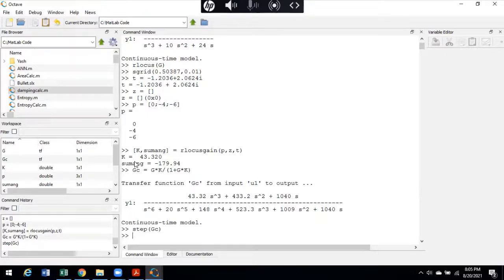We should be able to do that because it's a very similar skill set, except here we are designing the PD controller, but most things should be done on paper, which you should be able to do. Just maybe to illustrate, when I did that calculation, I followed the same step I've said to you. I've got the settling time was 3.548, and then divided by 3, you get the new settling time. From the new settling time, you get the new real part. From the new real part, by trigonometry, we can get the new imaginary part.